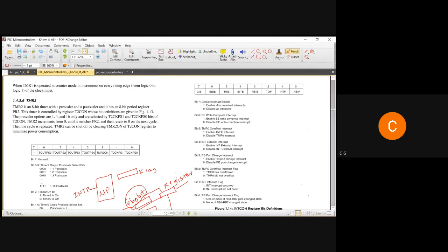So you will have to use a USB-controlled external arrangement, where you plug in a USB and it will have a parallel port output. And a diac triac requires only a trigger, so with a 5 volt trigger it can work. Or you can have fan control: you can have some D2A converter, which gives different voltage levels, and with that voltage level the diac triac will fire and control the speed of the fan. Up to that level people have gone.